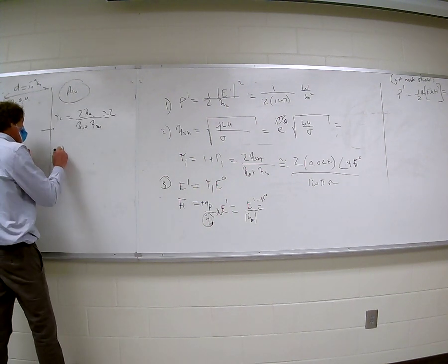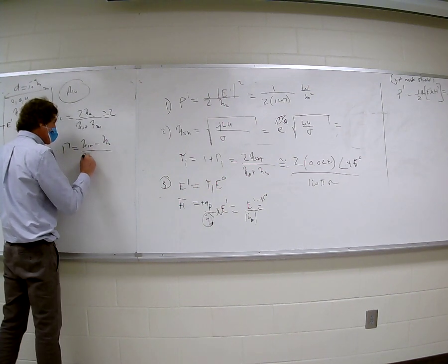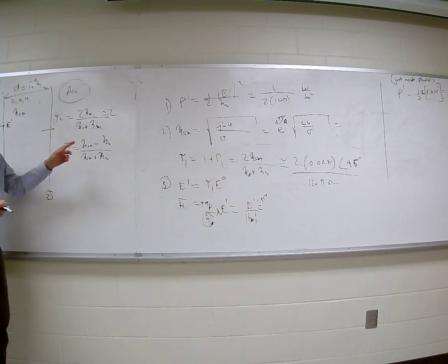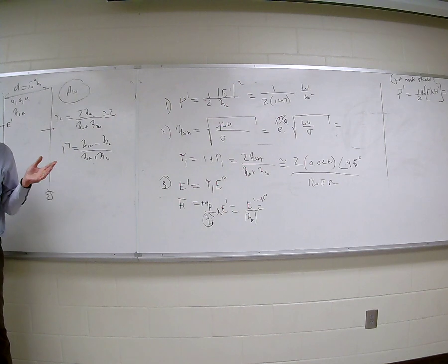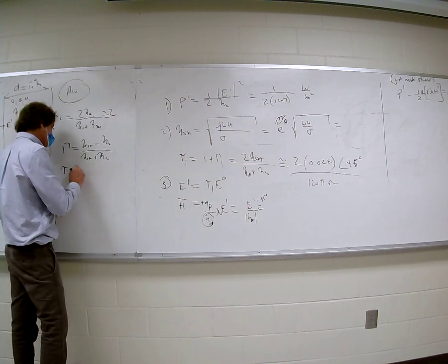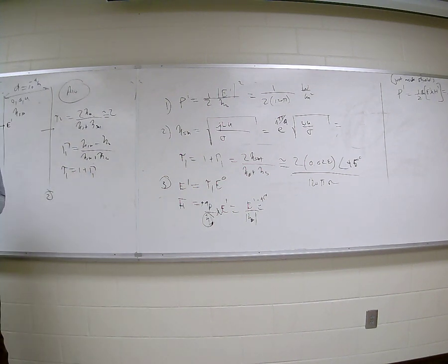They said that the reflection coefficient was eta shield minus eta naught over eta shield plus eta naught. Now, they took eta shield as strictly real. They didn't go ahead and put in the actual complex number. So when they got this equal to 1 plus the reflection coefficient, they got an error. I mean, it's wrong. I got you on that, so you have to include, when you're dealing with shields, low impedance values for good conductors, the angle to do these calculations, okay? I don't know how many made that mistake here, but there are a few, and I want to make sure you're clear on that. After that, what was asked for?